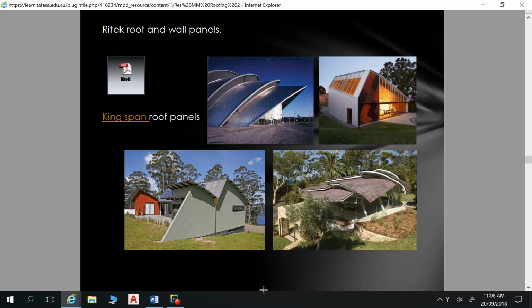The limit to the application of that stuff for roofs is that with the National Construction Code for, say, Climate Zone 5, where we are here down on the flat, you need to have at least a 4.1 R value for your roof insulation. And then Climate Zone 5 in the hills, at least 5.1 R value for your roof insulation. This only achieves R 2.5.